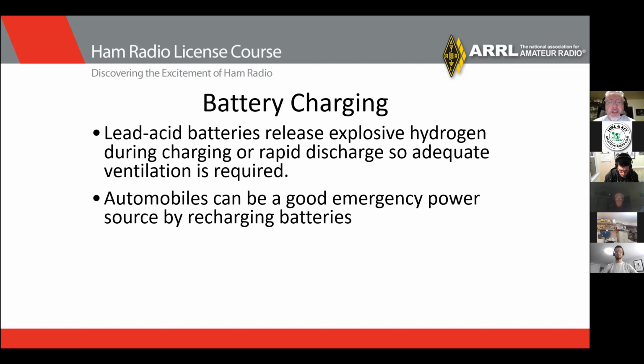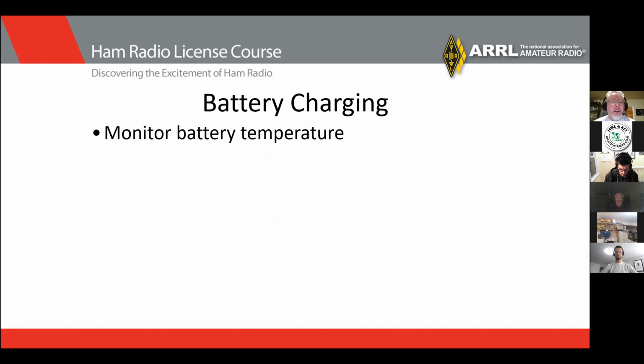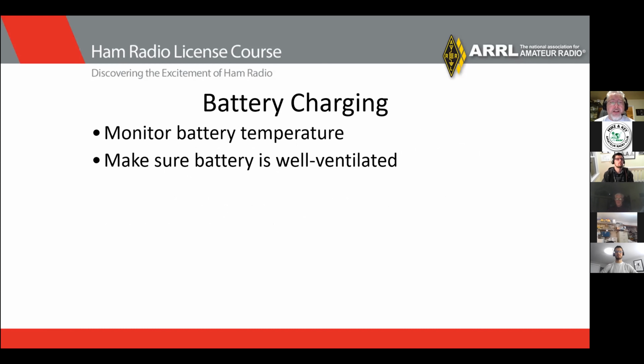Automobiles can be a good emergency power source for recharging batteries. A 12-volt lead acid station battery can be recharged by connecting it to an automobile's electrical system. Monitor the battery temperature. Make sure the battery is well ventilated.